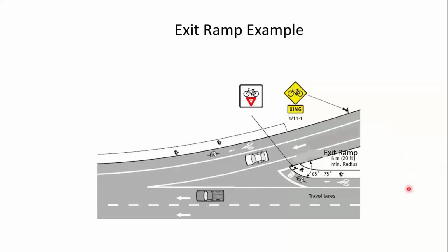And notice here, the agency has a bike lane here and also a conventional sidewalk, and they're showing the crossing point here. I'm not sure why they're not showing a marked crosswalk. I think that would be appropriate there. And then you can see the pedestrians and the bicyclists are now up top here on the other side of that ramp.